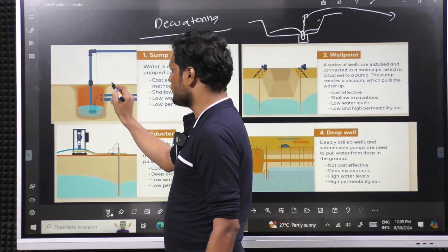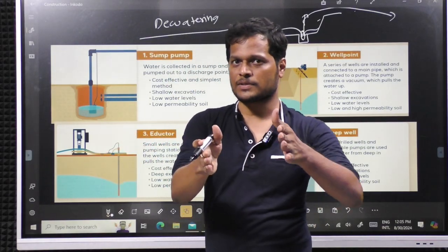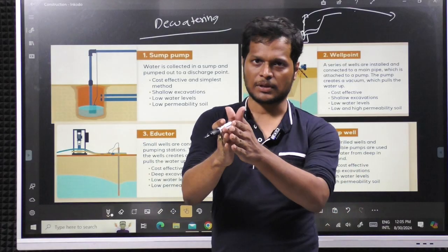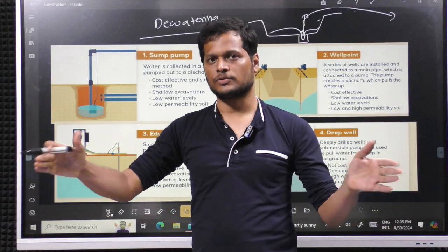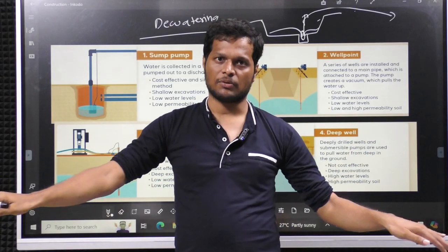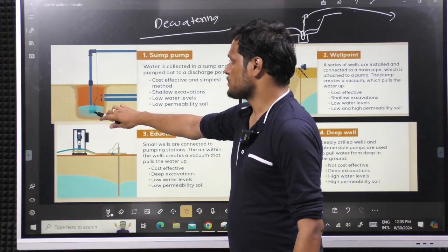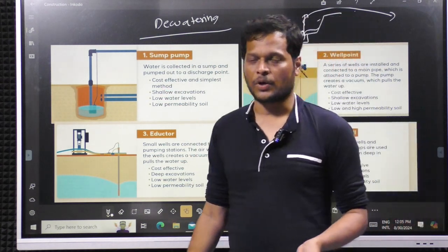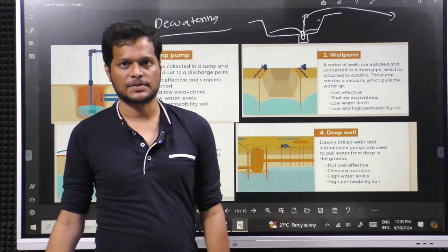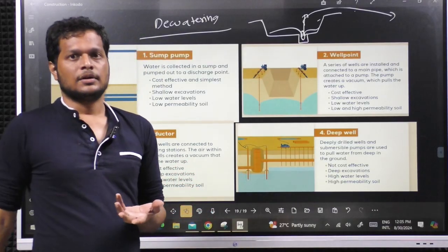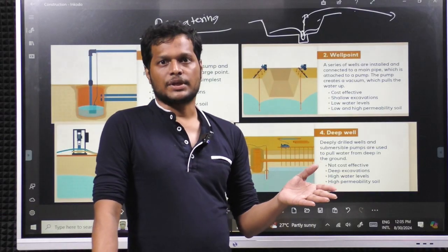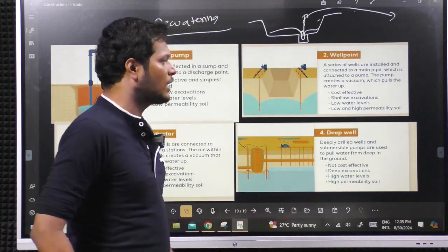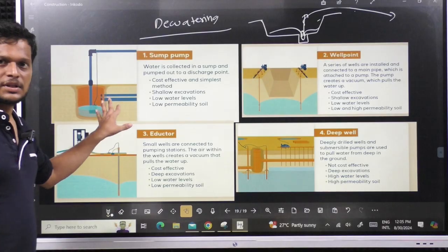So there will be a sump, generally at the corners. If the water is heavy, you can place sumps at two corners, so that some water goes to one side and some to the other. We maintain the slope and make sure all the water goes into the sump, and from the sump we do the dewatering. This is the sump technique, most commonly adopted for small sites. Even the apartments executed in IOCL faced a lot of seepage from the soil, and we excavated using these techniques only.